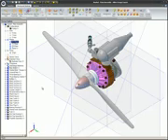This same sectioning behavior applies to assemblies as well as parts. The difference being that with an assembly you will need to indicate which parts in the assembly are to be included in the section view. Select the individual part by clicking on it in the Design Explorer, or select multiple parts and/or subassemblies using the Control key or Shift key methods in the Design Explorer in the same way you typically do with any list of items in the Microsoft Windows system.